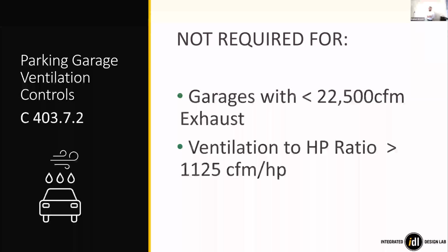So they've got some controls in there that are probably sensing carbon monoxide as exhaust. Or if they operate intermittently for less than 20% of occupied time, when you know that there's going to be cars in the building. One important thing on these controls is that they fail to on, so that if for some reason the sensor's failing to send signals, then the fans are just going to operate 24/7, for safety reasons, to exhaust anything out.